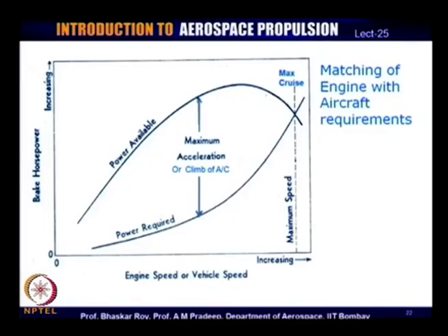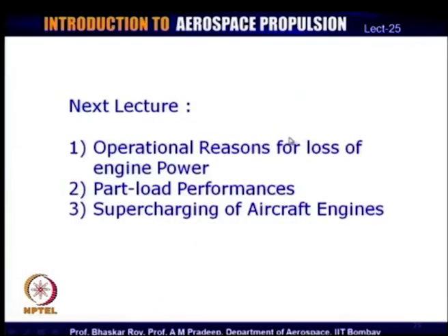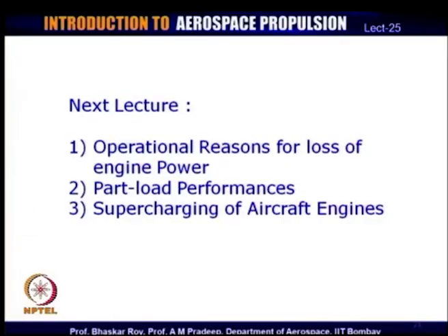This excess power availability from the engine is vitally important, because this is what makes the aircraft climb. Otherwise, the aircraft would not be able to climb from low altitude to the cruise altitude. So, this excess power requirement needs to be factored into the engine design, and this is vitally important for aircraft engines. In this lecture, we have now looked at various aspects of the engine that goes into the aircraft.